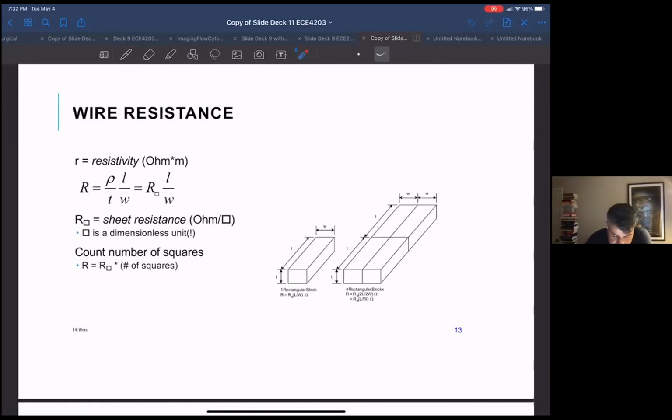Okay, now the first thing that's kind of confusing, and I don't know how to approach this, because it always tends to confuse people. The upshot of what I'm about to say is, when you're doing design on a chip, you are always trying to come up with numbers that are easy to deal with. You're trying to get rid of extra dimensions. An example is the sizing of a transistor in an inverter. Notice a lot of times in these tables in the book, it's talking about capacitance per micron.